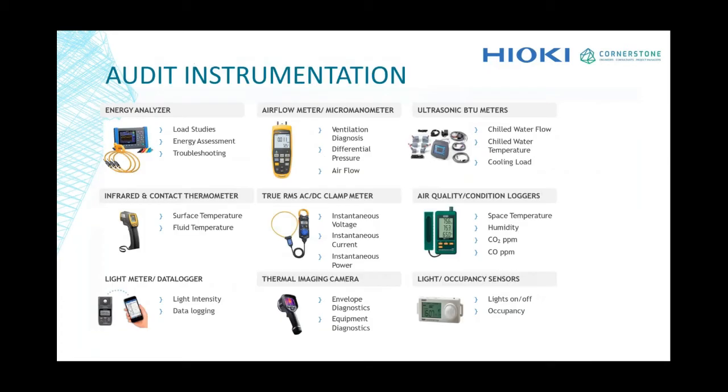Now, these are some of the equipment that we use. We are relying heavily on instruments, good quality instruments like Hioki's. They have a really good power analyzer that we work with to understand what the different loads in the building are, to log it. It's very easy to use, user-friendly. The interface is pretty straightforward, and it's easy to set up a power analyzer or energy analyzer on MDBs and different loads that we're working on. So that's something that we work with.